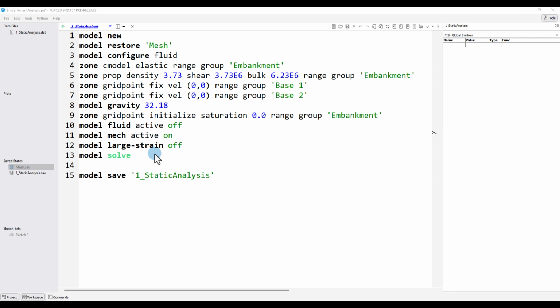Note when following the steps about to be shown in this video, the volumetric averaging will be used as the contour method, and maximum, minimum, and interval values will be specified. The reversed setting will be used in some cases. Each new plot is created by clicking the drop-down arrow, then New, followed by Plot.